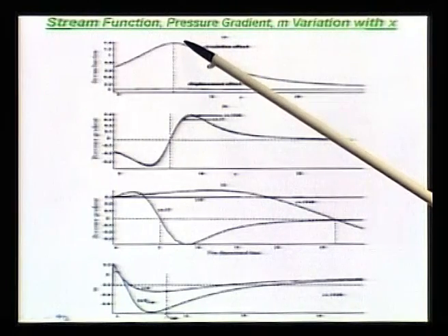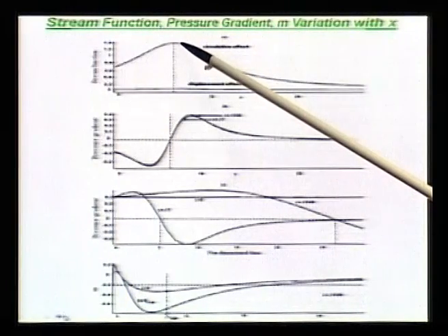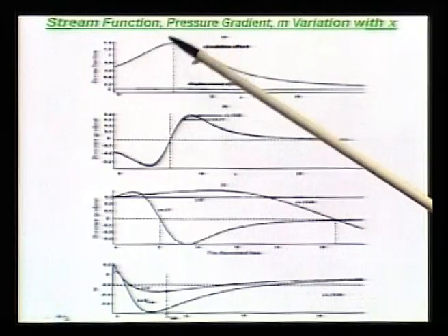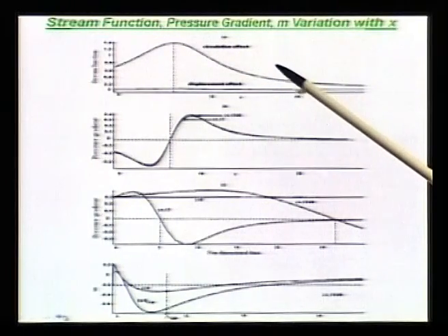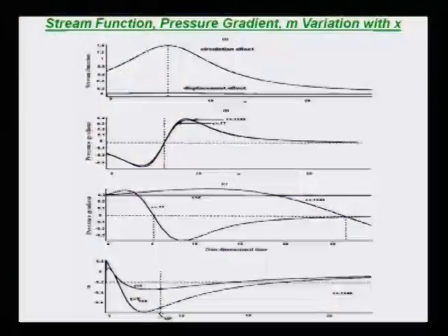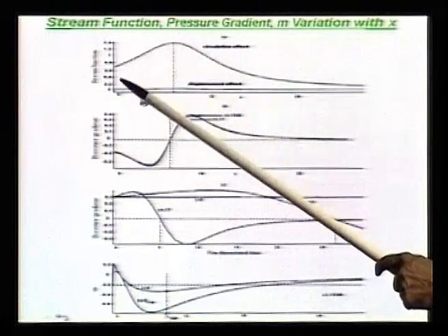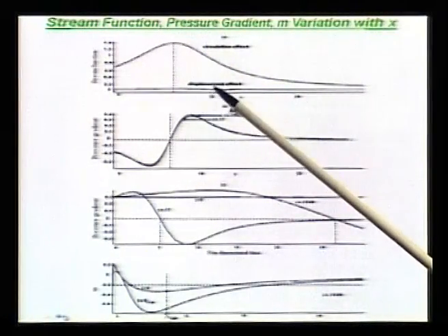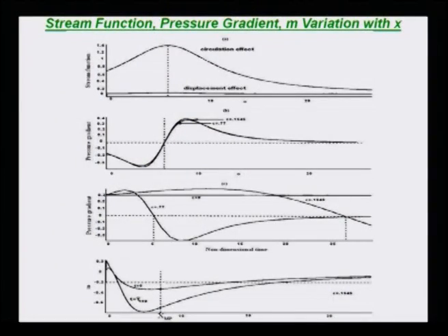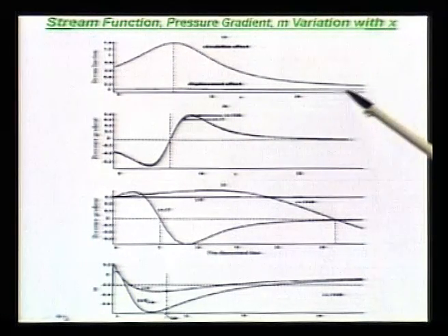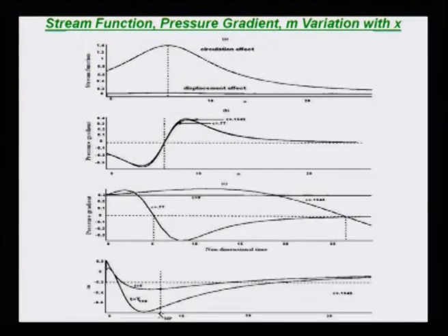So, of course, the disturbance is maximum in the vicinity of the cylinder and it falls off, and this is due to the circulation effect, the gamma part. If I parameterize the value of gamma and work out an expression, this is how that circulatory effect would be. However, the displacement effect remains flat. Okay? It remains the same for all x's. That is what you are seeing.